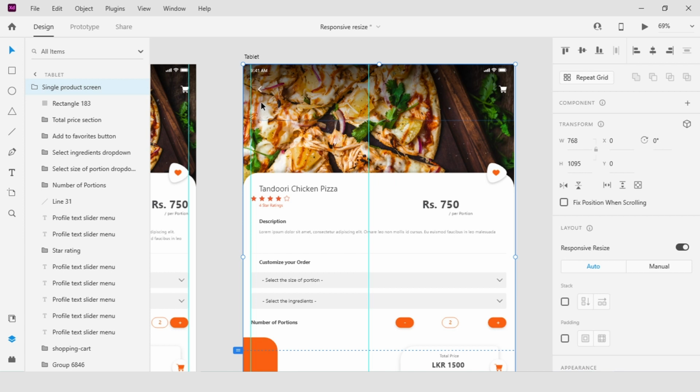This is using something known as percentage based layout rather than absolute or pin layout. So if I double the width of my design, it doubled the space between the carrier and this little back arrow icon. I have the ability to change that behavior so that it does the right thing.